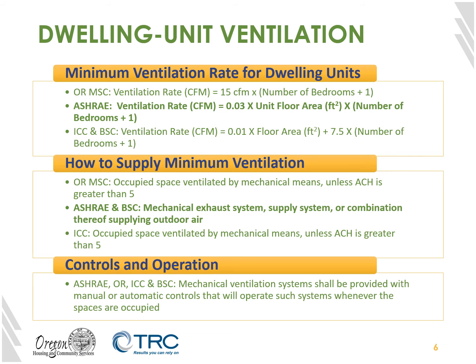Next, each guide dictates how the ventilation may be met. Each requires some form of mechanical ventilation, either exhaust, supply, or balanced, though the ICC and Oregon Code allow for natural ventilation in more leaky buildings. For a full description of these ventilation system types, we encourage you to watch the first module in this series. Finally, each guide describes the controls and operations requirements, the key being that ventilation is controlled to run continuously whenever the space is occupied.